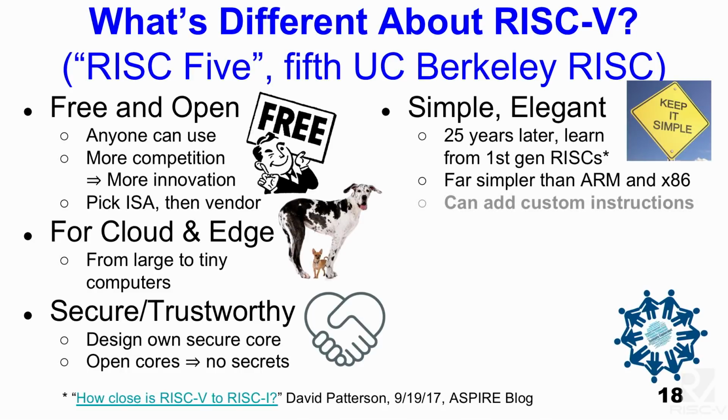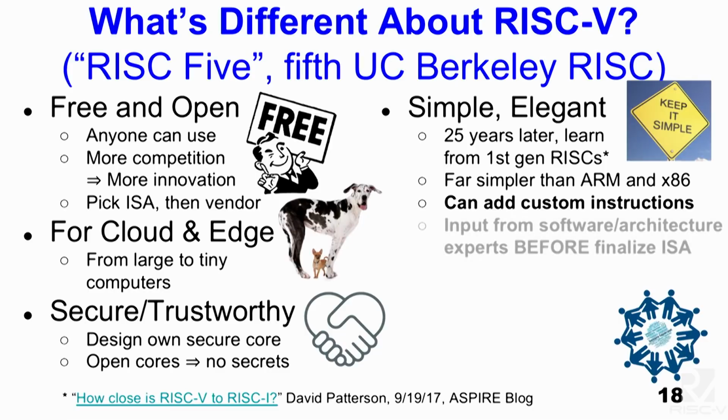And it's a new idea in an instruction set in that in the past you had to be binary compatible, upwards binary compatible, and if you stuck it in, you had to leave it forever because you don't know who's going to run things. RISC-V doesn't do that. RISC-V says you can add custom instructions. It won't break the software stack because the software is only based on the core, not on the extensions. And I'll explain why we need the custom instructions.